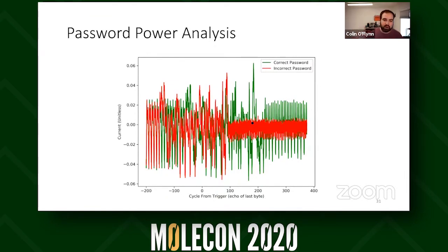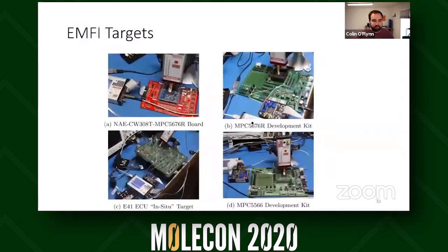The other thing I want to point out is that I talked about cases where you had the ability to reverse engineer the code to figure it out. This is an example of how, even if you didn't have that, you can still find out a lot about the device by observing the difference between the code paths. If you try to boot a fake image versus a real image, or send a wrong versus correct password, there's a lot you can observe that tells you how it's executing.